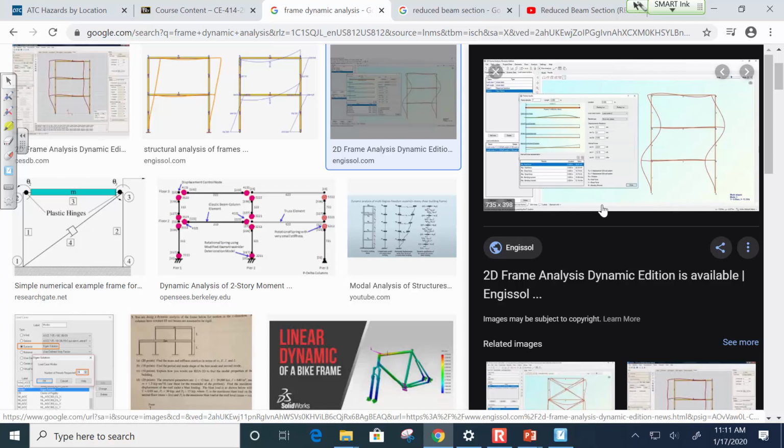Now this is a cantilevered beam, right? Building sticking out of the ground, cantilevered beam. So where are the worst case forces? At the top story or on the ground story? Building's going like this. Where are the big forces inside the building? Up here or down here? It's down at the bottom.